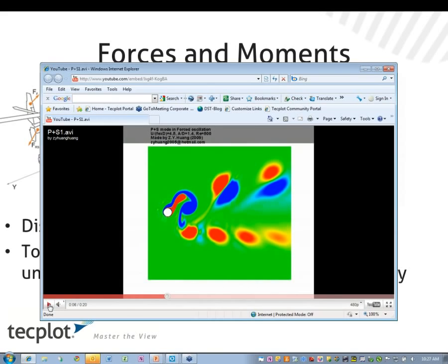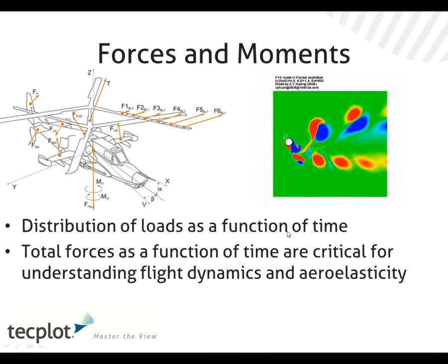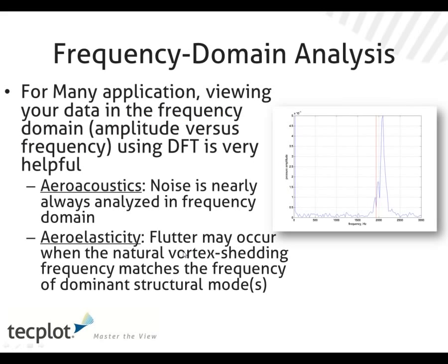the sort of thing that happens also in the cables that hold down various things like offshore oil rigs, and you get these vortices shedding off of it, which actually force the motion of the cable, and then that in turn actually enhances the vortex shedding. And in certain situations, that can get totally out of hand, like in Galloping Gertie, and cause structural failure. And so that's certainly an area where looking at an unsteady simulation can be perhaps more informative and certainly more interesting. I don't know if anyone's ever simulated these bridge disasters, but it's been fun to do so.